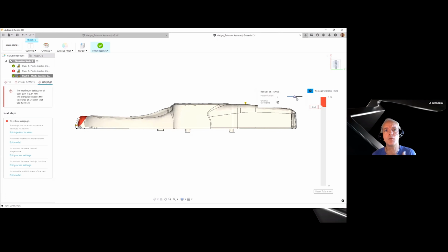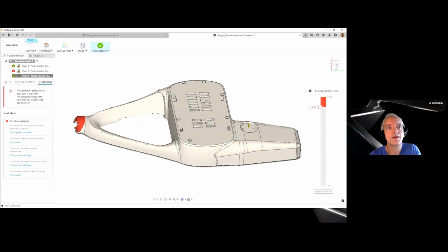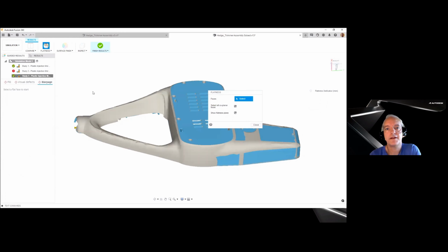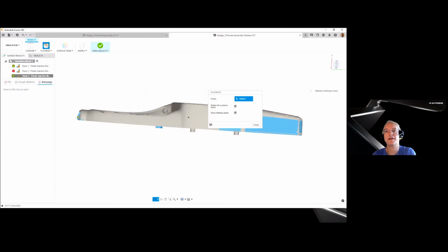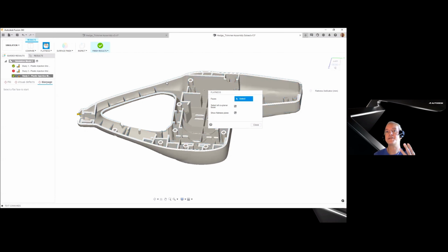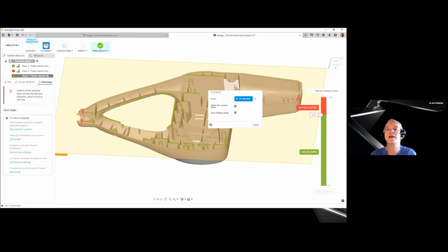So one of the things you can do now is go back to magnification 0. We now have a property for flatness. Yep, activate that. If you turn the part around, this is a part where you have two mating surfaces, right? If you select a face, now we can see how much out of plane deformation there is.